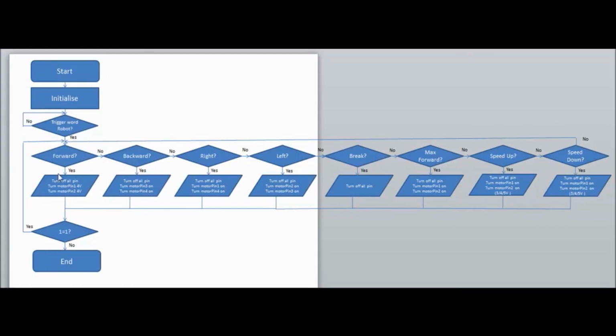Okay, we start and end the flowchart with the start and end block. First is the initialize and define block, which happens where the ports are given a name, defined, and the variables, such as the speed variable, are initialized to a given value. Similar to the Bluetooth flowchart, the same pin names and variables were used to be consistent. First, a trigger word must be set for security reasons. To keep the security simple for this project, it is called robot.